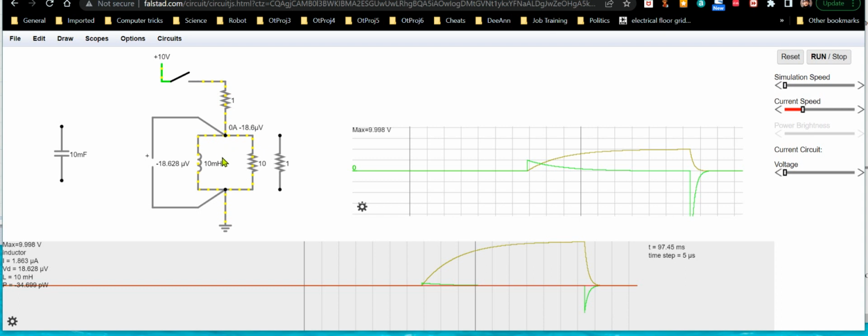If you know anything about inductance, and the voltage by Faraday's law, the voltage equals the derivative, the d/dt, times the inductance. That's the voltage it's going to generate. Well, because of that basic concept, you put 10 ohms with 10 amps going through it. Because remember, this is 10 amps to begin with. Well, we put a 10 ohm resistor in there, so that's going to generate 100 volts.